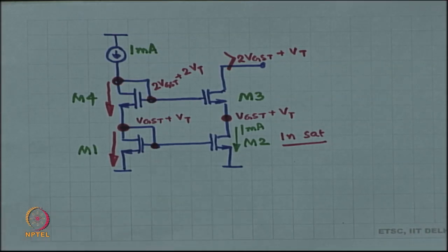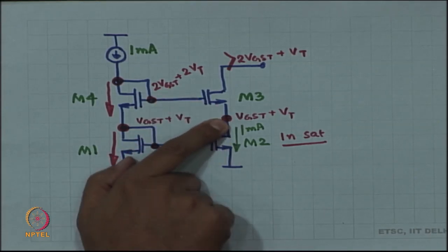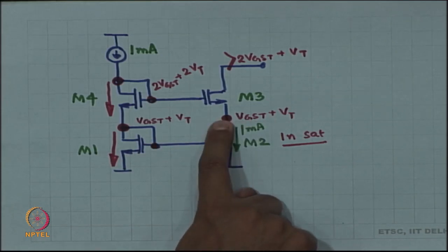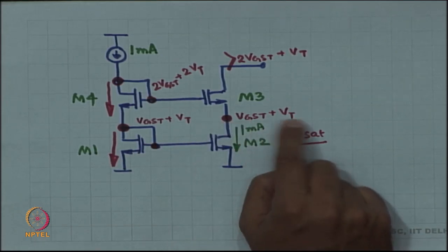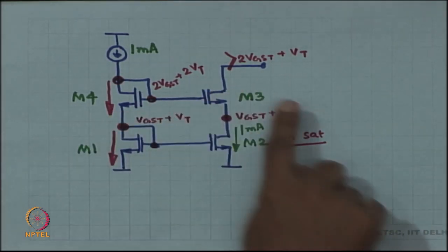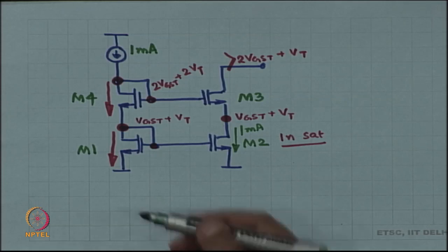So there is this graceful degradation going on. You have got some room. The lowest possible voltage here is just VGST, but actually the voltage is VGST plus VT, which means you have got room for graceful degradation of up to VT. Now, there is one more thing to observe, one more really nice feature of this circuit.